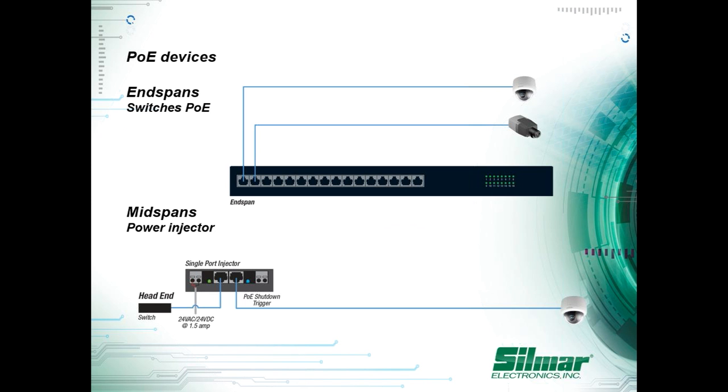So when we're budgeting for PoE, we have to also take into consideration that class, because I cannot budget 7 watts for a class 3 item. I have to actually budget the 15 watts. It's max load, because that's what the camera will reserve.